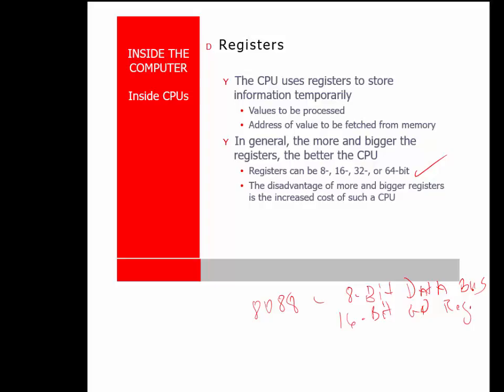There weren't any chips to support 16-bit processors yet. All the memory devices were 8 bits. All the buffers and all the other I/O devices were all 8 bits. They could not sell the 8086. So they came up with the 8088, which was the same processor internally, but it was 8 bits externally. They sold a bunch of them.